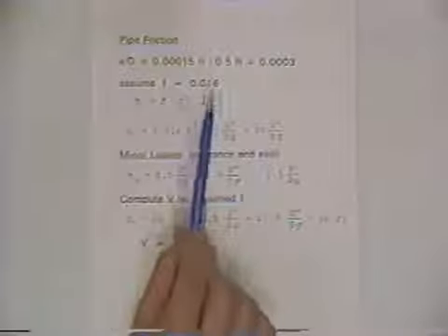So, having used a bit of judgment with our Moody diagram, I assume 0.016. That's not arbitrary, it's a pretty good guess. I'm saying I've assumed it, and I can easily come back and check it because once the problem's solved, I know the discharge and I can compute the Reynolds number and see if I'm in the right range or not. And if I'm not in the right range, I'll just go through the computations again.